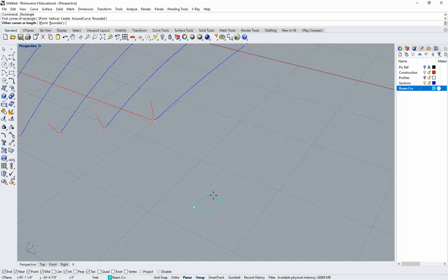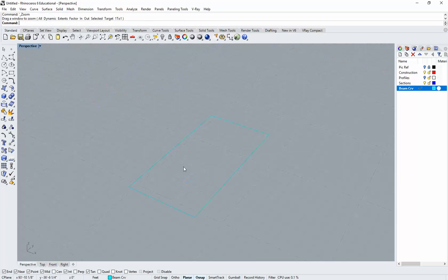And I'm going to set the size of this thing. So the first thing I'm going to do is set an 8-inch dimension for one side. And for this, I'm going to type in 8, and then make sure you type in inch. So the quotation will make it 8 inches instead of 8 feet. Remember, you're in feet units, so you have to type in 8 inches manually. Hit enter, and then for our overall, in this case, it will be the width, which actually is the length, but the other dimension here will be 16 inches. Okay, you can go ahead and click enter. So now we have, and I can double check on that, a rectangle that we've drawn at 8 by 16.